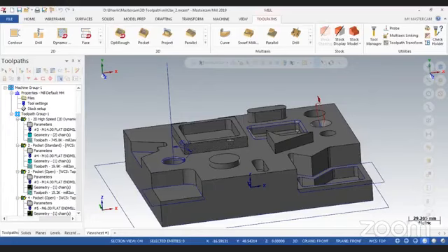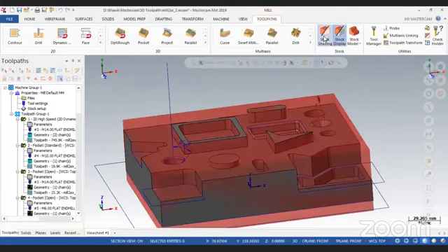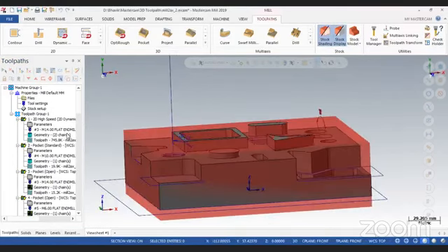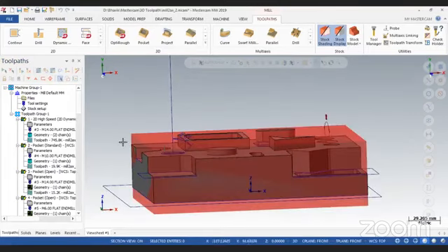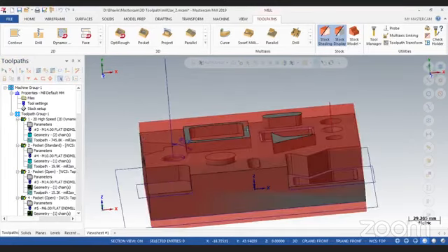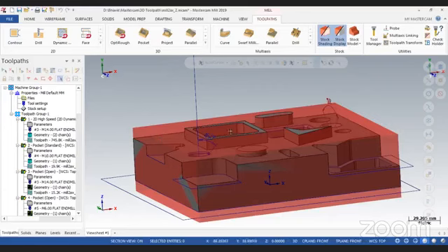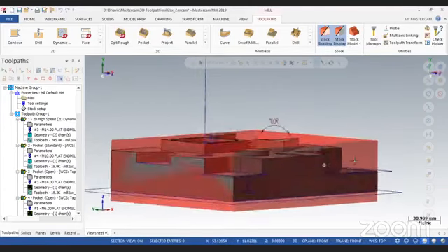So that gear blank will be inserted, and then gradually teeth will be milled. Teeth will be generated through milling, say a hobbing cutter. So it will be generated from a blank part. In this manner, in Mastercam also we need to define a blank part like this. So here is my main blank part, which I have defined, and the software will generate the final product by removing material from this blank part.